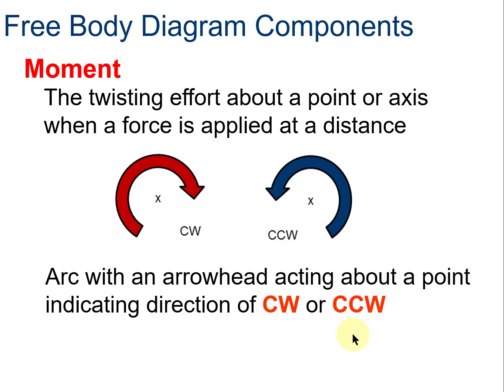So the reason we're worried about both of these is that we're going to work on a bridge, and we want that bridge to hold up, so we want it to not move. So we don't want it to rotate, we don't want it to move left or right, up or down. So that's why we need to think about forces and moments. And also this free body diagram we're going to talk about more in a moment is a way to do some bookkeeping with forces.